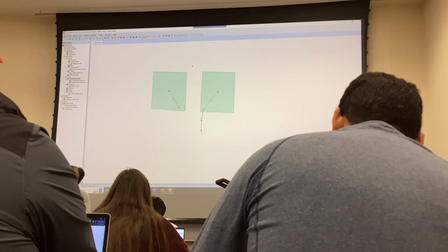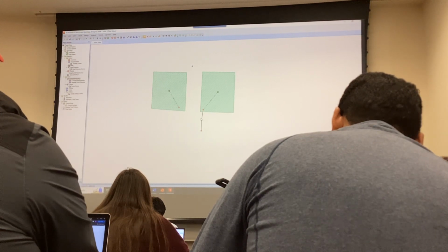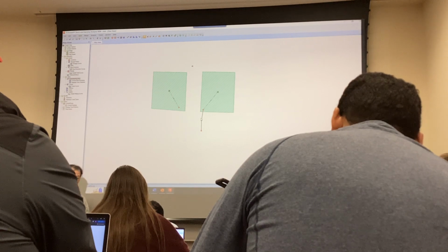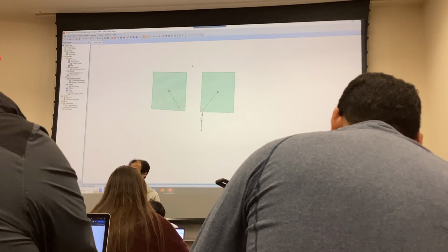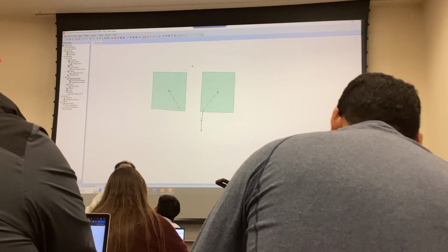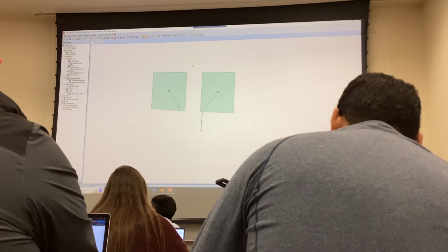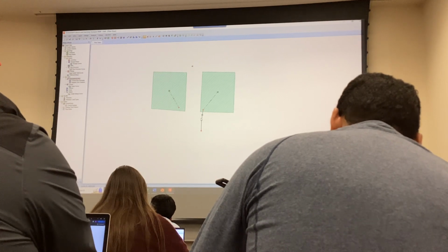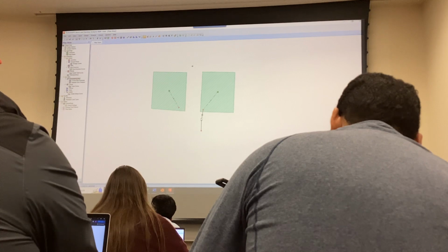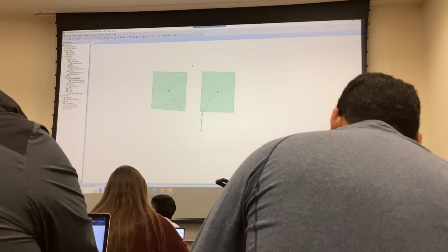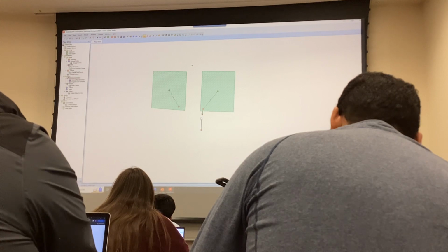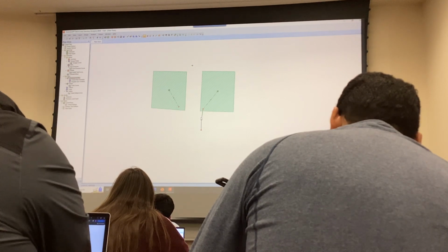So the next step. So now I have a detention here that will basically store, but it doesn't have the control of outflow that I want. That means I'm still releasing more flow than I'm allowed to, right? So what do I do? Okay? The next stage is I want to design my outlet structure. So what do you do when you design your outlet structure? Basically, you make a sketch of the different events. Right? You put it on over here, and you start putting in the type of outlet control you want.